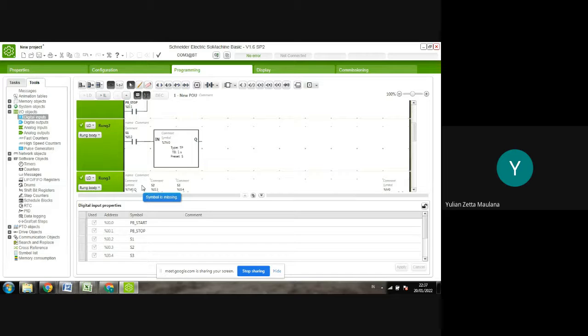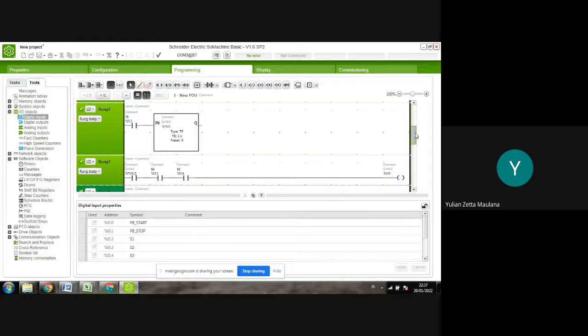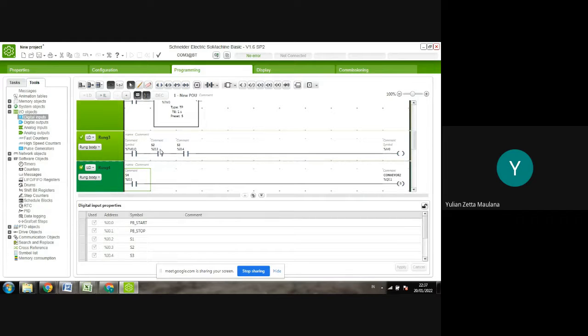There's nothing wrong with the label. There's nothing wrong with the box. But what happens if after 5 seconds there is nothing happening here? It means that the opposite happened. There's something wrong with the label. Maybe the position is not right. Even though one of the sensors detected the label, if both sensors do not detect the label, it means that the label is not in its right position.